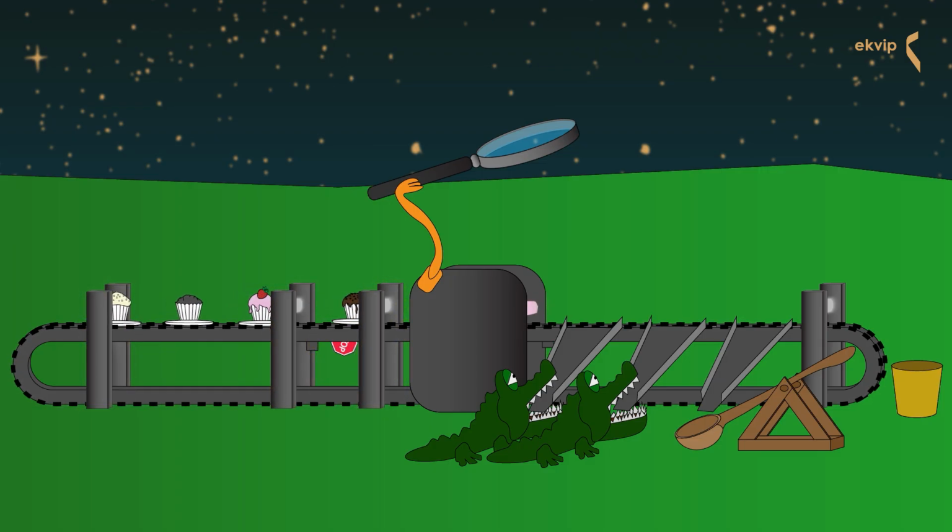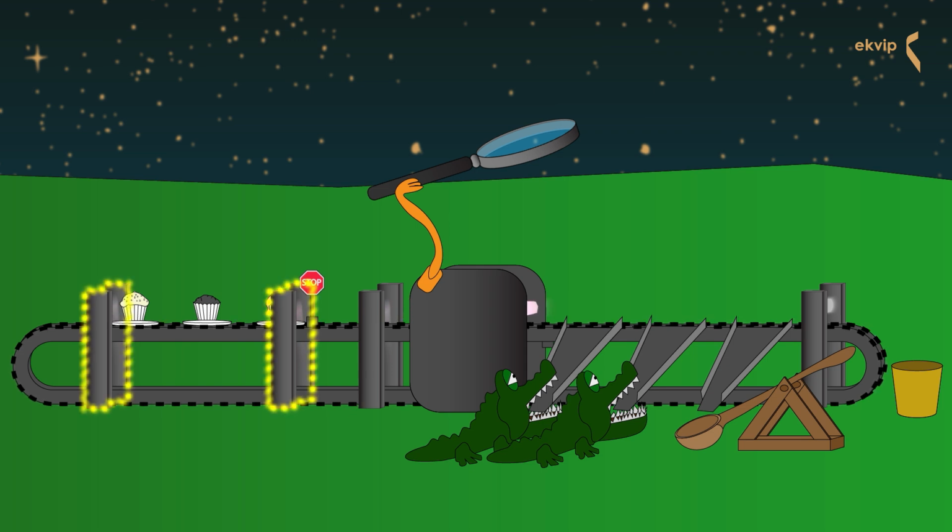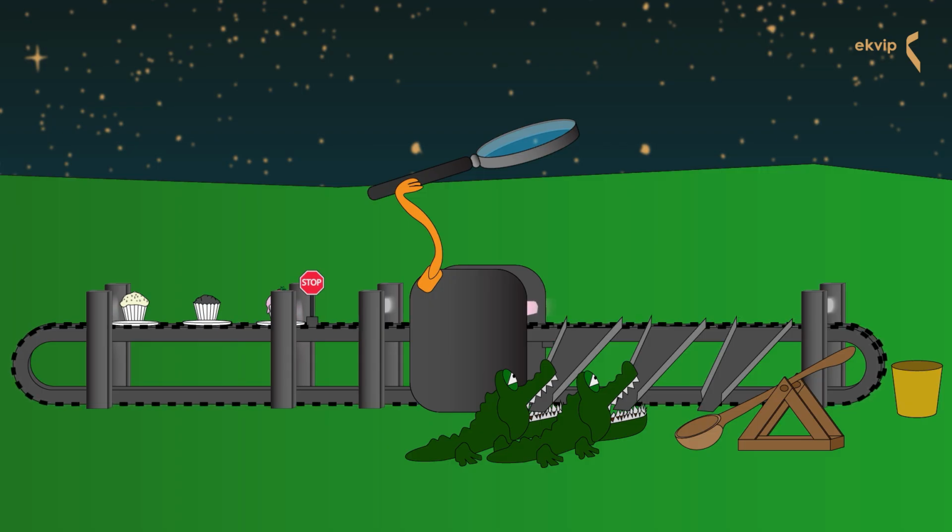When a cupcake passes it, a stopper is raised in front of the second light barrier. This prevents the following cupcakes from moving forward and avoids congestion at the next station. If the space on the conveyor belt between the first 2 light barriers is occupied, meaning both sensors are blocked by cupcakes, the turntable must wait before placing another cupcake onto the conveyor. This is the buffer section. Once the first light barrier is free again, another cupcake may follow.